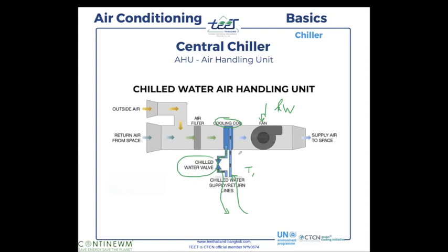So this needs a special device that is called a BTU meter. Sorry, I write very poorly with the mouse, but I need to find a smart way to do that. You install a BTU meter to measure how much energy from the water this AHU is absorbing, because this is 80% of the power consumption.